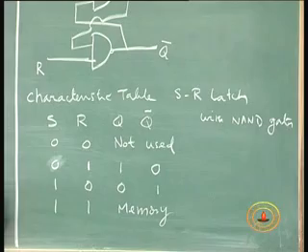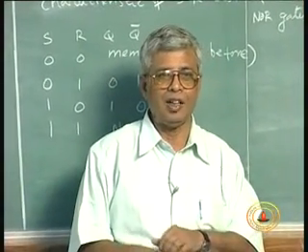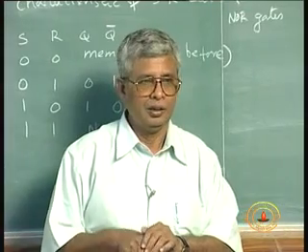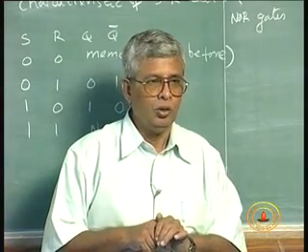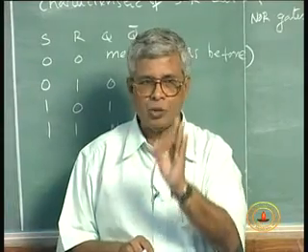Because of the fact that S does not set it, S bar sets it. R doesn't reset it, R bar resets it. So we now have a basic mechanism of storing a bit of information. A bit is 1 or a 0.